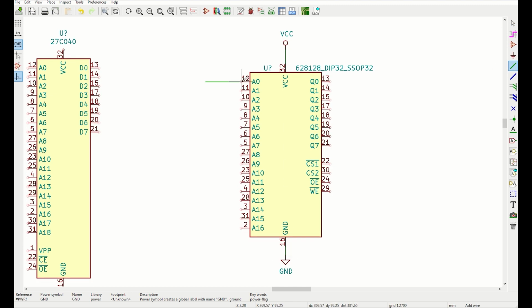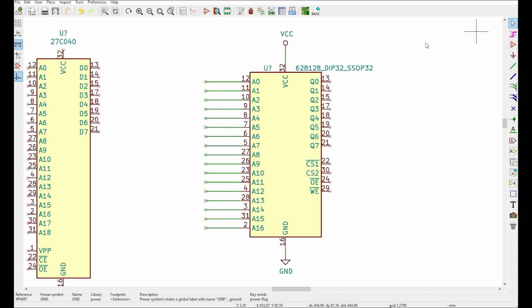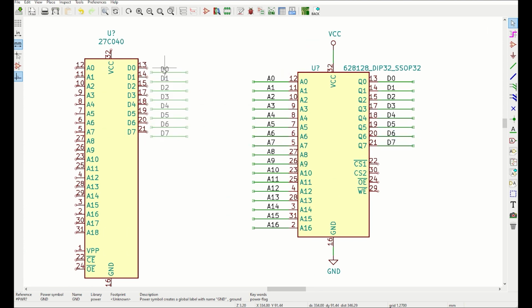I'm using the free KiCad software, and once you get used to all the shortcuts, it's actually very powerful. Now this is one of the features in KiCad that I particularly like. When you draw a line, you can just press Insert, and the line gets replicated just where you want it. The same thing happens with labels. You just label the top element, and if it starts with a 0, it'll auto-increment every time you press Insert.